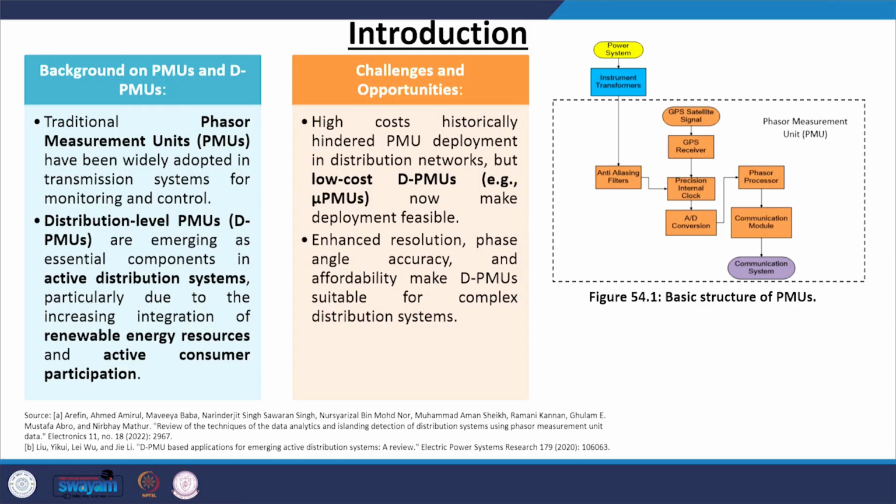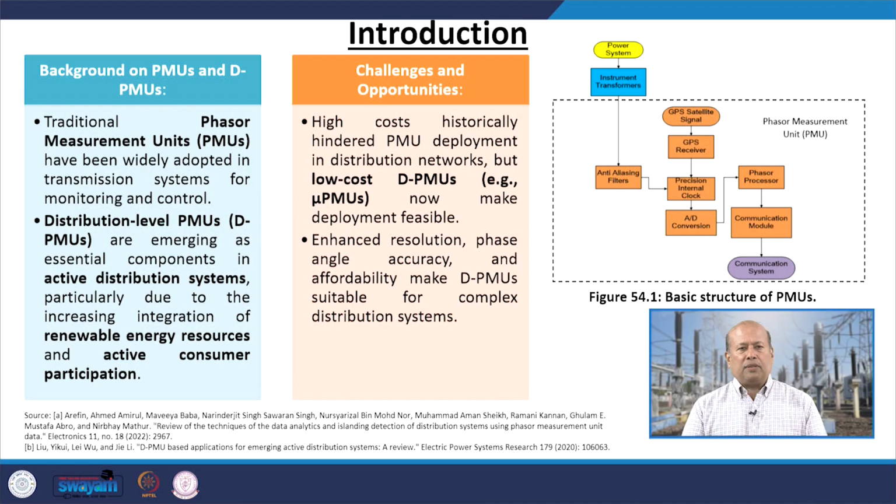Now, traditional phasor measurement units, PMUs, have been widely adopted in transmission system for monitoring and control, and they are emerging as essential components in active distribution system too, particularly due to the increasing integration of renewable energy resources and active consumer participation.